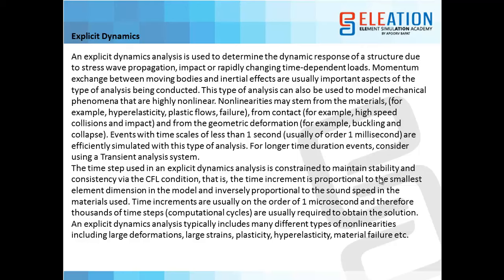If your time step is very small, then make sure that your element size is comparatively bigger, and if your element size is small, then you should take a higher time step, so you get results in considerable solution time. The time increments are usually on the order of 1 microsecond, and therefore thousands of time step computational cycles are usually required to obtain the solution.